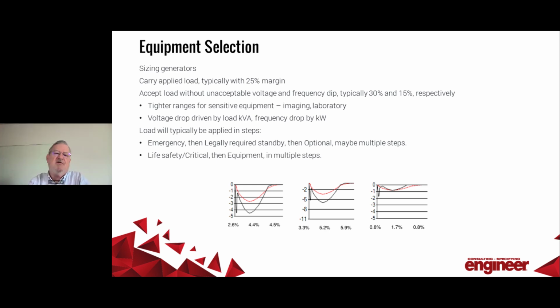Also, when sizing generators, of course, the main requirement is they have to be able to carry their load. They may have enough capacity to support their whole connected load, or they might be big enough for their highest priority loads and have a load shed system that drops low priority loads as necessary to keep the high priority loads on. And typically, a generator is sized with about 25% headroom to allow for future expansion or to allow for flexibility in moving loads around from one step to another.